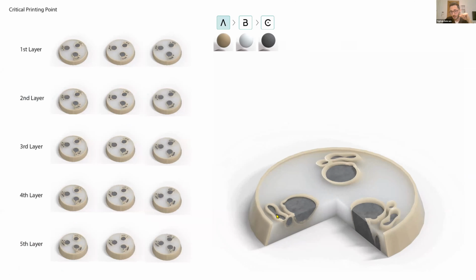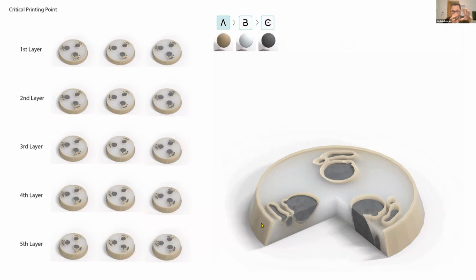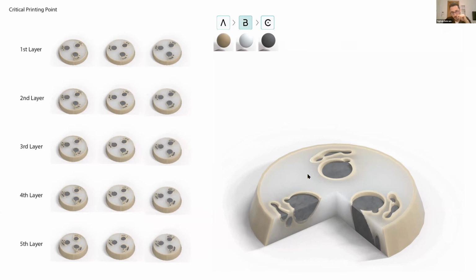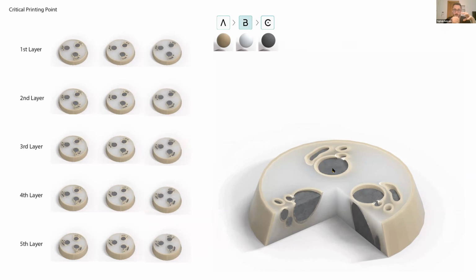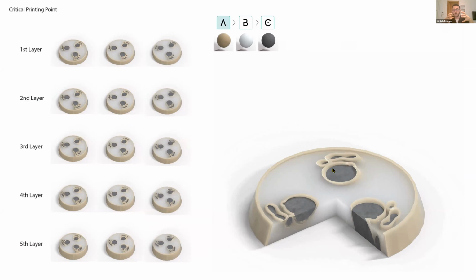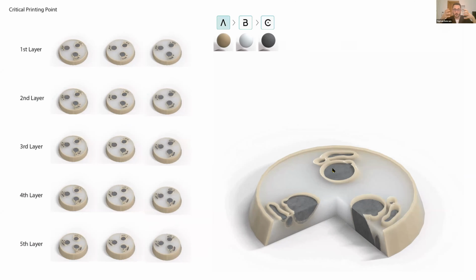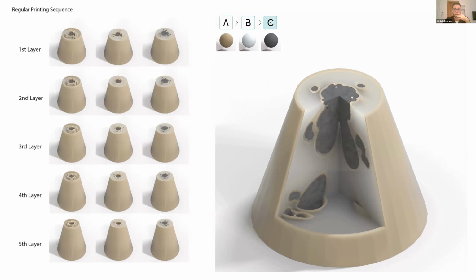As you can see, the outer shell and the inner shell, the wax and cellulose mixture parts, are 3D printed. And then a certain amount of pure wax is poured, and then the concrete is poured. This is happening because we need supports in these areas, and the system should go layer by layer because we cannot go that fast. But in the prints where we don't need supports, a certain amount of layers can be 3D printed, as seen in the outer shell and the inner shell, and a certain amount of paraffin wax is poured, and then a certain amount of concrete is poured as well. So we can make things faster if we don't need supports.